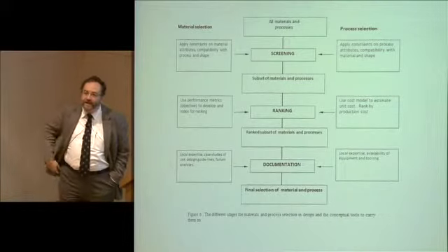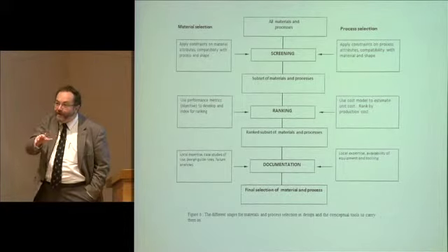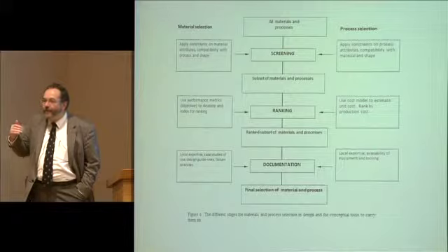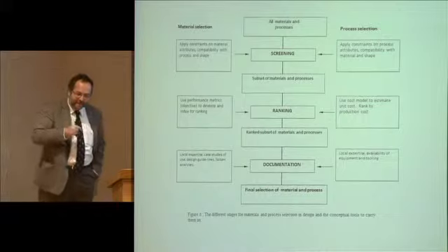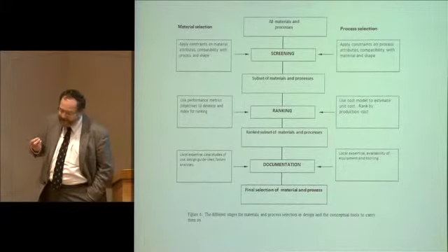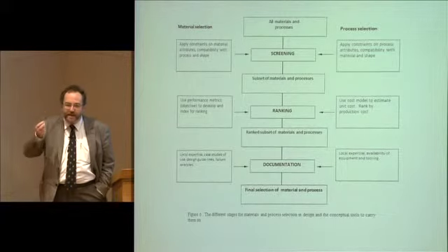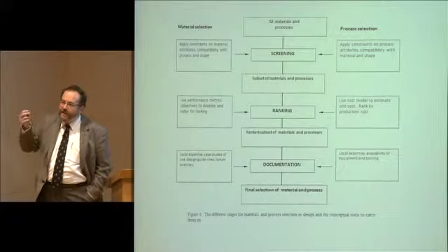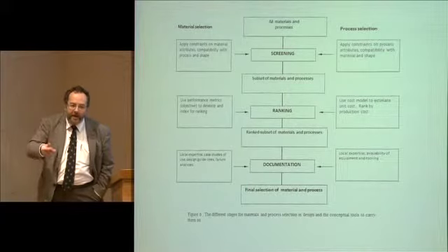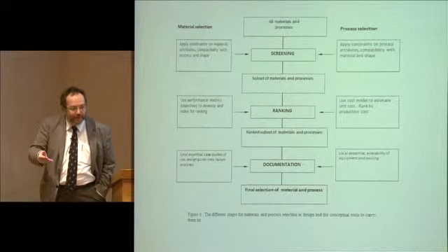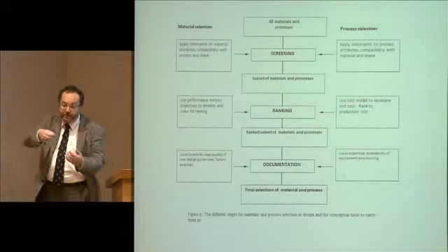So you say, I want someone who's both good at mechanics and good at materials. I have loads of guys who are good at mechanics, loads who are good at materials. I need someone who does both. So what I do is that I then rank by a performance index. And the simple idea is that the index is the combination of properties that make a material relevant for a given shape, a given load, a given stress, and a given objective. And that's what we're going to call a performance index.